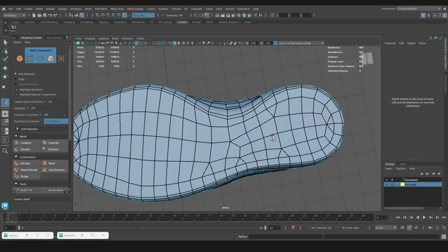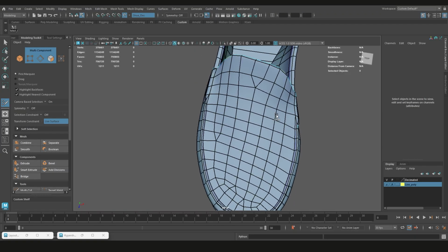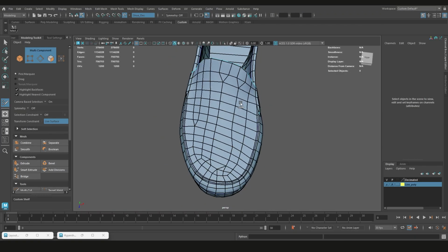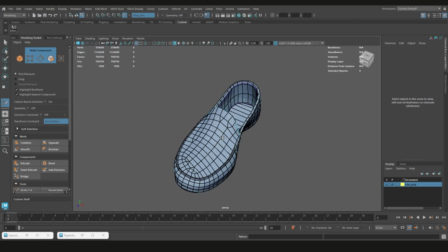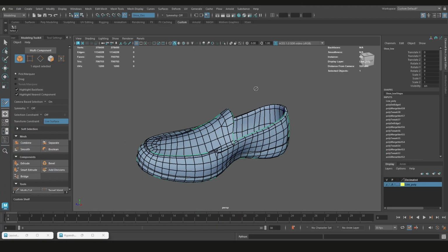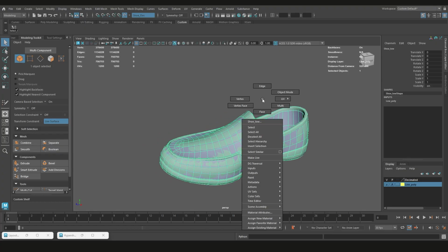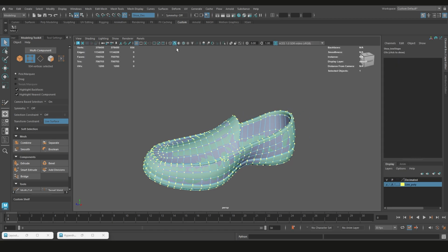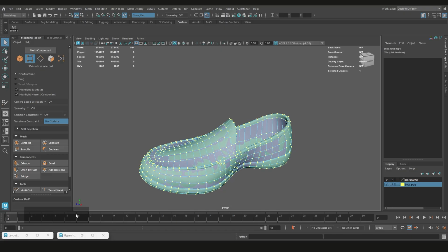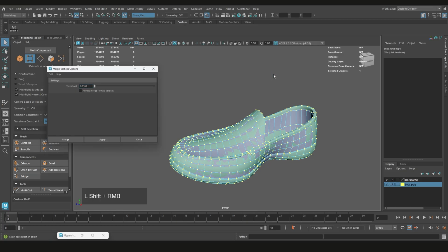But anyway, you get the point of optimization now, right? So you might also do one of these ones here as well. So let's maybe do this one together. Okay, there we go. So we're going to go back into object mode, Control Shift Q, and click on this one, Alt Shift D, and I want to go to vertex mode, and then Control Shift A to select everything, and then Shift right click and drag, merge vertices, merge.